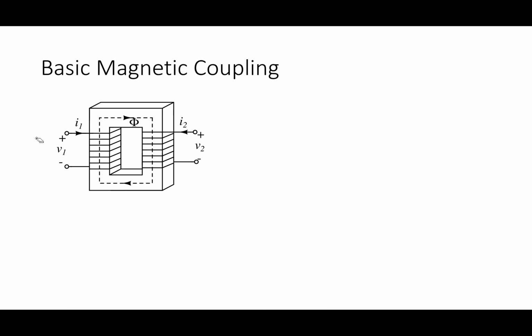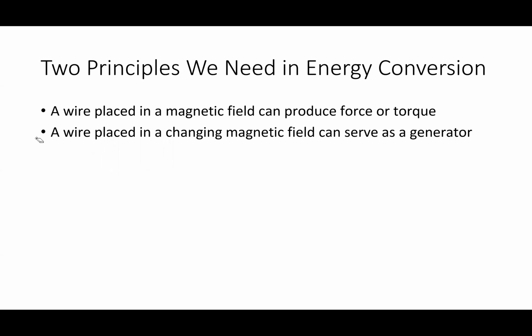All right. So there's good reason for that. In fact, anytime I'm hooking up a PV inverter or something to the grid, usually I do it through a transformer. Okay. No, it's not high passing. I guess let's stay away from words like that for now. It's basically ensuring that I have what I'll call DC separation. Sometimes that's called galvanic isolation. Some of you may have heard that term.